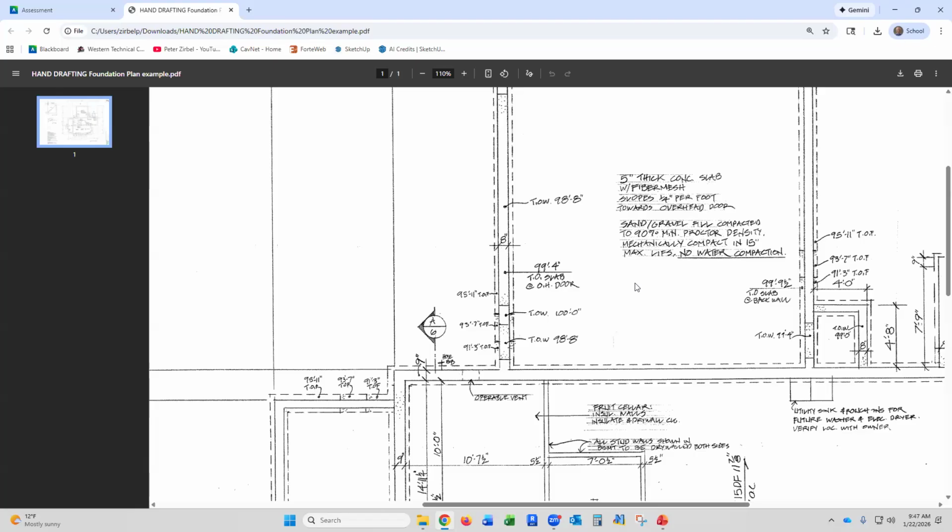So what has to happen is there's no sense me digging out my garage to 8 feet deep because I only have to get 4 feet down for frost, right? So why would I dig this whole garage? There's no dirt in here. This is air, but this is dirt. It's just the slab on grade. So I only have to dig down 4 feet for a little trench here. So there's no sense for me to dig all this out here. But we need to have our footing continuous and step down. So what's happening is the footing comes out, it steps up, and it steps up until it gets to that 4 foot. So there's probably 2 steps in there.